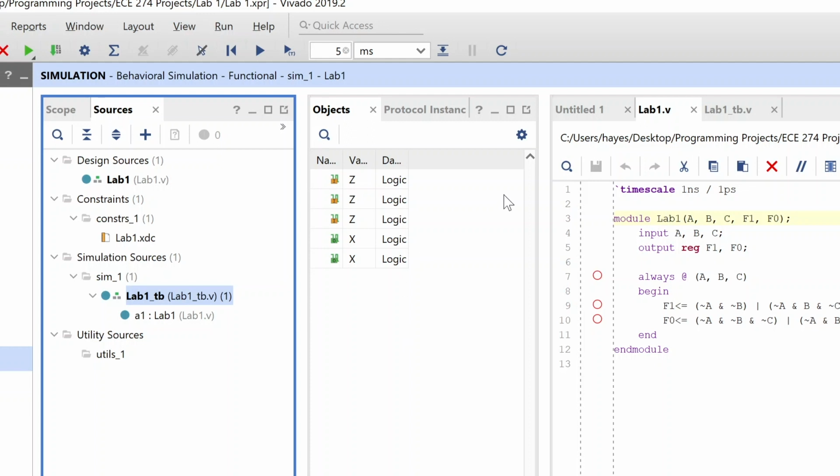You can also relaunch the simulation, which is useful after making updates to the test bench file, by clicking the circular arrow that appears on the very top interface in Vivado. Also located on the same interface bar is a button with an input box to specify how much longer you want to run the simulation for, which is very useful for more complex Vivado simulations.